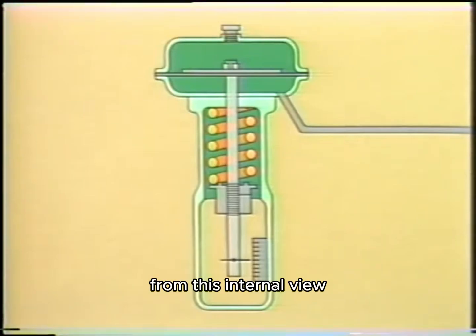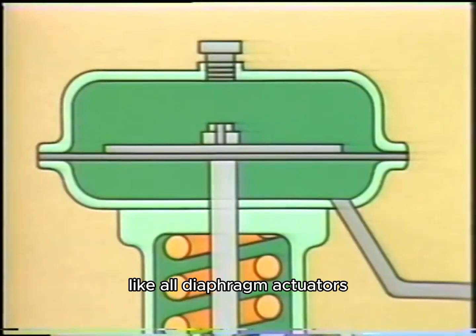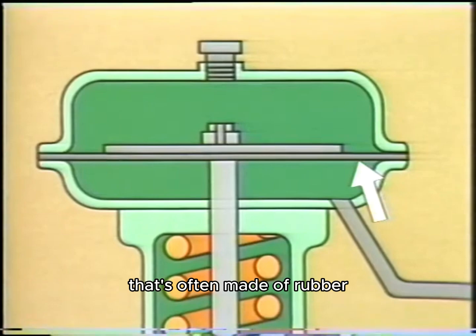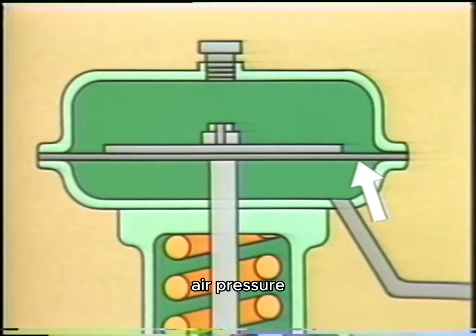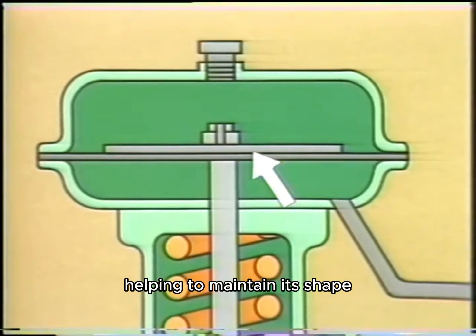From this internal view, we can see how this actuator gets its name. Like all diaphragm actuators, this one has a flexible disc called a diaphragm. That's often made of rubber. This is the component that is directly acted upon by air pressure. A metal plate stiffens and supports the diaphragm, helping to maintain its shape.